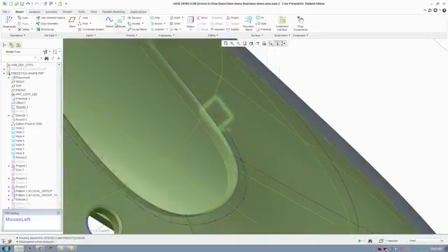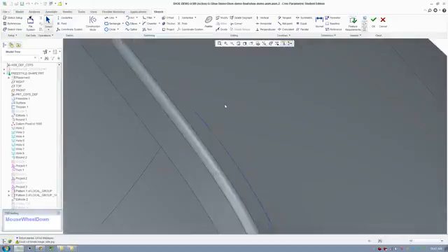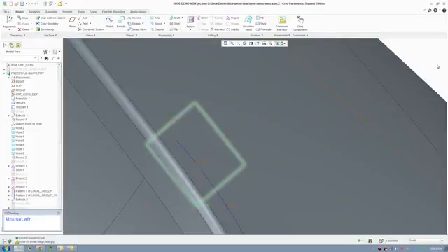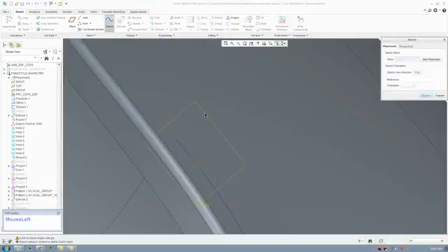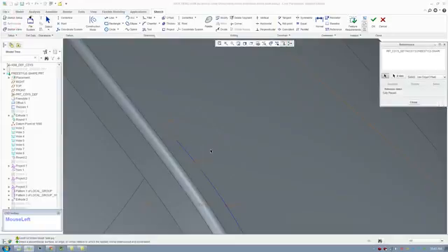We're going to draw our design, our stitch, and it's basically a ring shape. We're going to draw on here, so I selected that plane. I'll show you that again. So go to sketch, select this plane we just created, click sketch, and to reference these things we click on reference, click that to load that in and close.